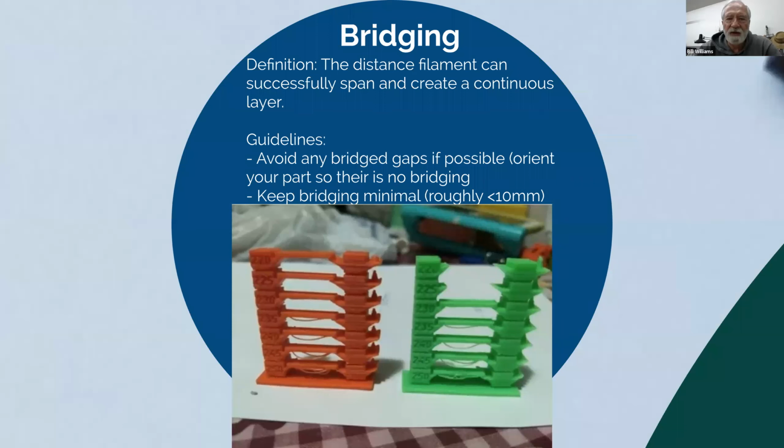Okay. And what about that buffer idea? I didn't understand what you were saying there. What does it mean? There's a tolerance that you have to take into account? Well, yeah. For example, the bed flatness, let's say the bed is a little bit out of skew. Well, then your nozzle to bed distance is different. And then that means your layer adhesion will be different depending on where the part's at.